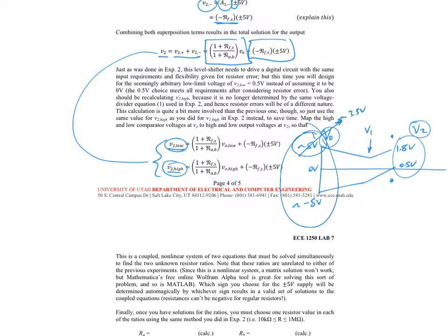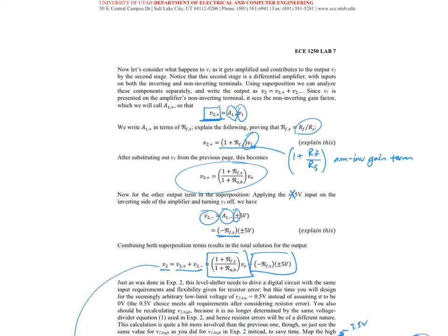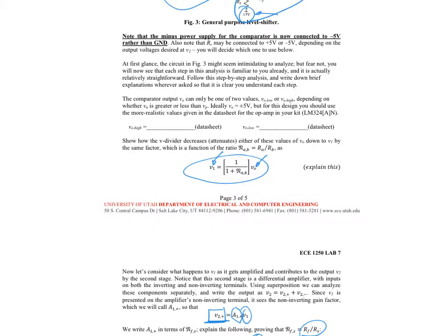So if you're expecting something like 3.5 volts for that, what about the negative 5 volts? Should you expect negative 3.5 volts? Well, it turns out if you look at the data sheet, which is what it's asking you to do here, for this guy, the data sheet will just come straight out and give you around 3.5 volts. And it calls this VOH, the high output. And then it'll give you the VO low output only for when VEE, which it's calling the low source, the negative source, is grounded. It only tells you when it's grounded.